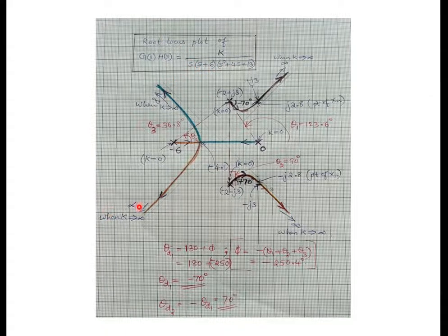So that it will have accurate branches, the points, everything. Even the angle, as I told you, can be measured using a protractor. You can have a scale, and here I have given all the root locus branches with a different color. This is actually red color. I do not know, when I take the picture it is showing something else. Still, there are 4 different colors put for 4 different branches. There are 4 branches because there are 4 poles.